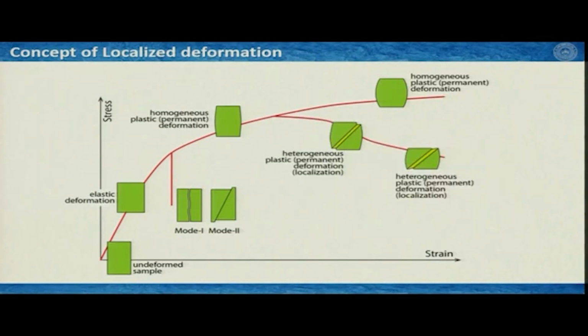and there is another possibility that we can have strain softening, and if that happens, then we see a localization here in the sample, and this localization, or this shear surface that we see here, is characteristically different from what we have seen here in the brittle domain. So, this is ductile because the rock is accommodating deformation without producing any fracture, and this is brittle.